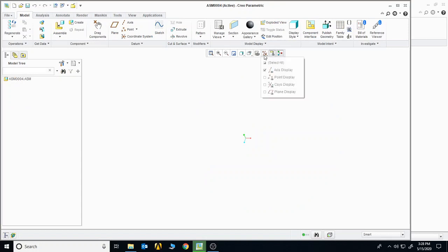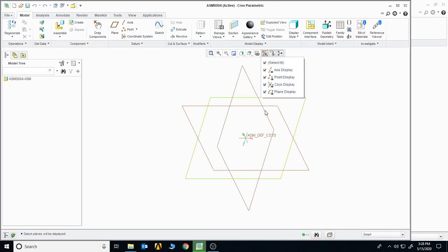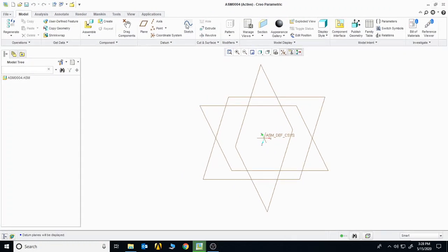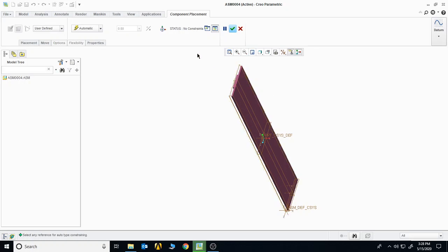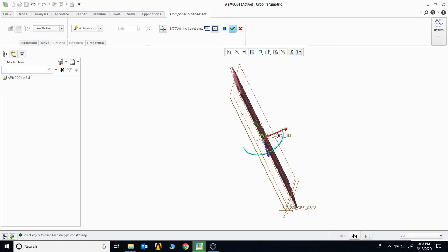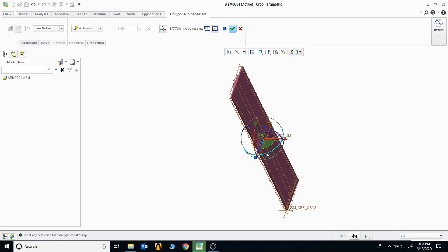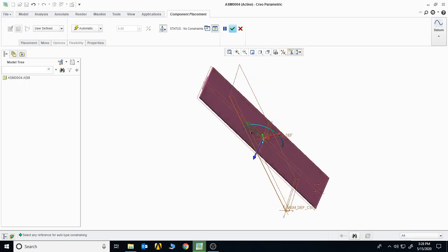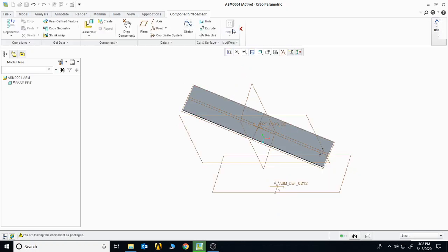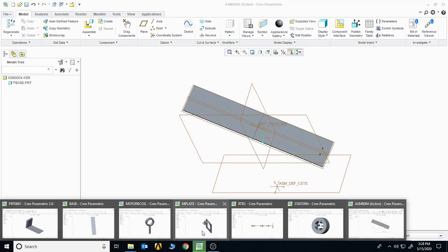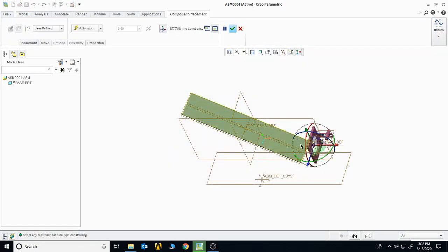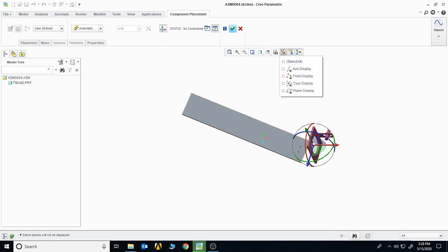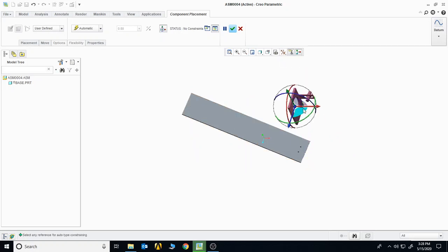That is simply just an example of assembling different geometries to make a complex structure. Click on assemble. I will first import the base part. So you have imported this particular base part. You can change its placement if you want, or you can change its angle accordingly. Click on OK. Now I need to place this plate over it, so I will go into the assemble. I will select the M plate. Okay, so this plate has been imported here. I can change its movement accordingly.